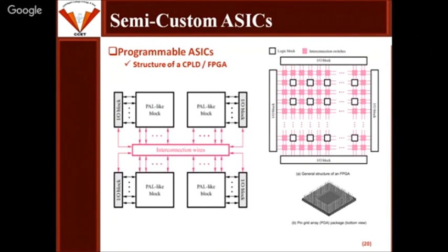If the current is passing, the relay will be on and that device will be connected, and if the relay is off, that device is not connected. So depending upon the program, those different logic cells will be interconnected, and then we can have the particular design fabricated on the FPGA.